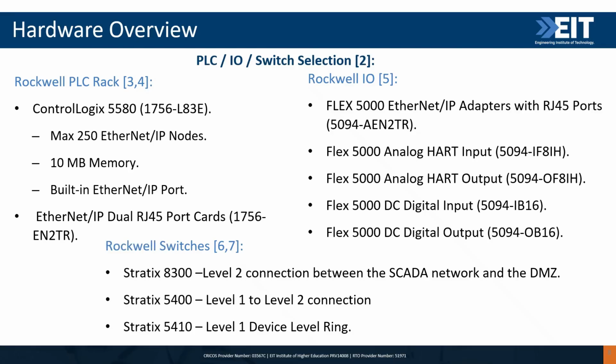The Rockwell switches will include Stratix 8300, which will be placed in level 2 between the SCADA and the DMZ, Stratix 5400 between level 2 and level 1, and Stratix 5410 will be utilized for the device level ring network for the field devices and remote I/O.